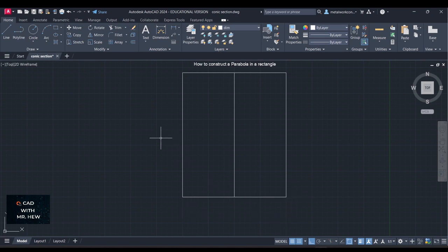All right, we're gonna divide the base into 8 equal parts. So we're gonna draw a line, any angle, any length. And what we're gonna do next, we're gonna scribe 8 arcs of the same radius starting from right there at the end, right where the cursor is.